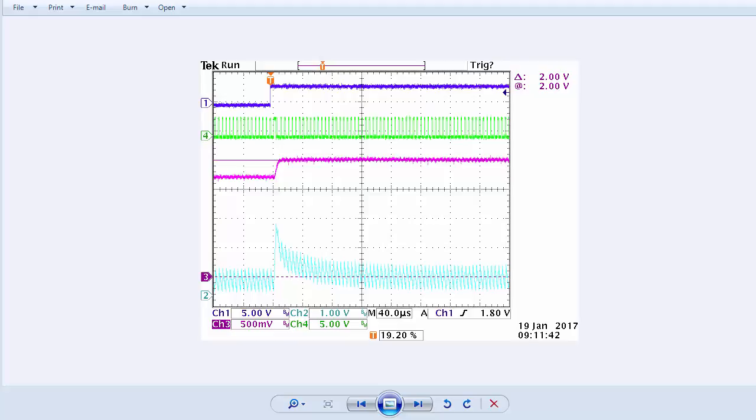Sometimes we get lucky and a compensator approximation using only a few coefficients matches the ideal compensator well. Sometimes we're not so lucky and the approximation is not as good as we would like. Generally, the more coefficients, the better the approximation and the greater the computational complexity. These are the trade-offs that need to be evaluated in every system design.